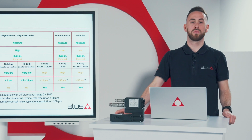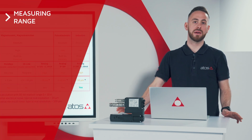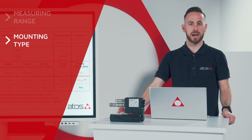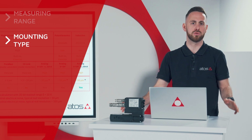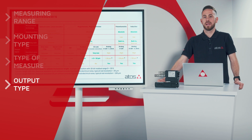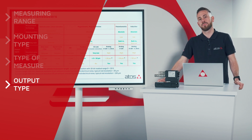The main parameters of a position transducer are the measuring range, selectable by the user and based on the mechanical stroke of the cylinder. The mounting type, external or internal. Built-in solutions are the most recommended as they are not subjected to mechanical displacement due to mechanical shocks or vibration on the machinery. The type of measure, absolute or incremental, we will explore this aspect shortly, and then the output type, SSI, analog, incremental TTL, IO-link, field bus are just some of the interfaces available on the market.